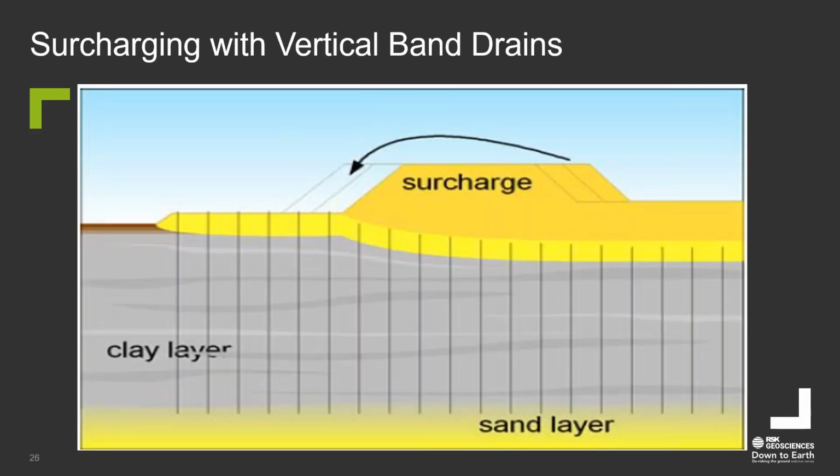Surcharging is applying an embankment of soil above your required final level, and that increased height adds extra weight that will help the soil to consolidate. And what's really going on here is we've got weight and the water pressure in a clay soil. It's a low permeability, very soft or soft clay soil, which will settle a lot over time, and therefore will generate a pore water pressure if we apply some load to it.